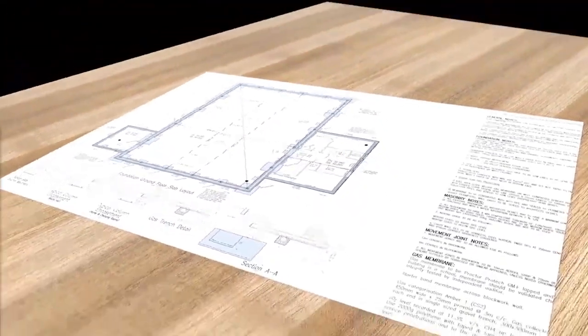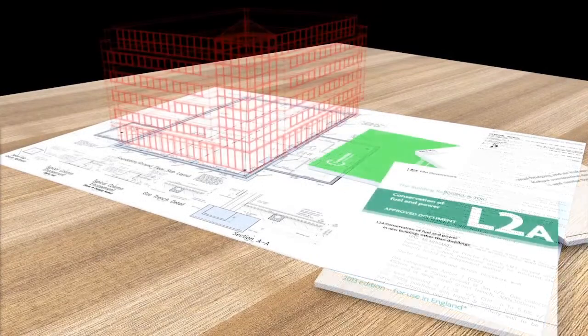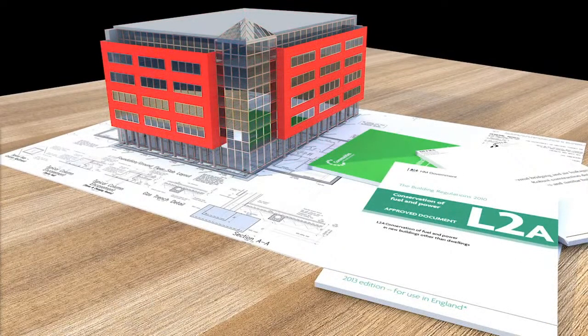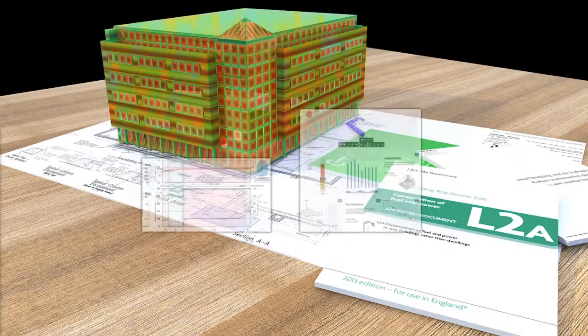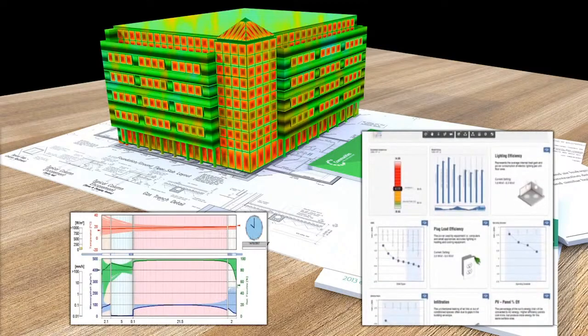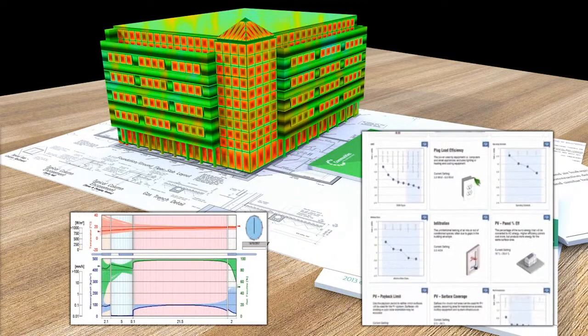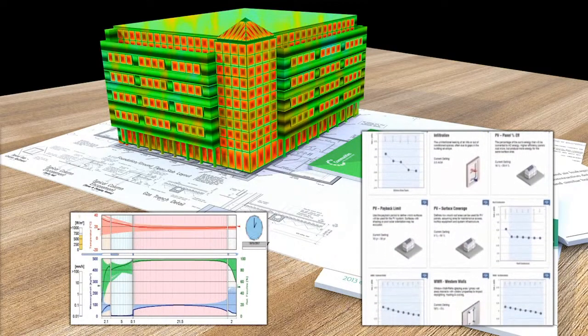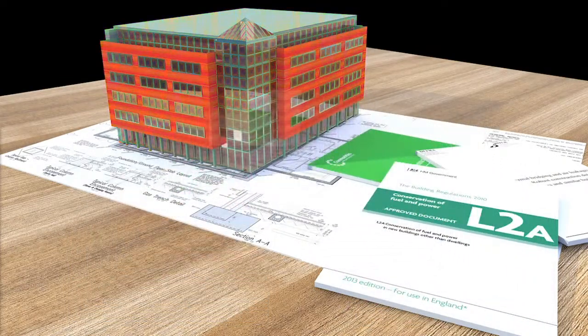Calculating the intricacies of heat flows and energy performance can be accounted for using a variety of modelling tools, from simple U-value and SBEM calculations through to complex BIM models and advanced simulations. The degree of modelling complexity required will vary from one project to the next. Depending on the system used, these models can account for everything from basic insulation levels to complex life cycle assessments and allow comprehensive optimisation of the building design by accounting for all these factors we've discussed.